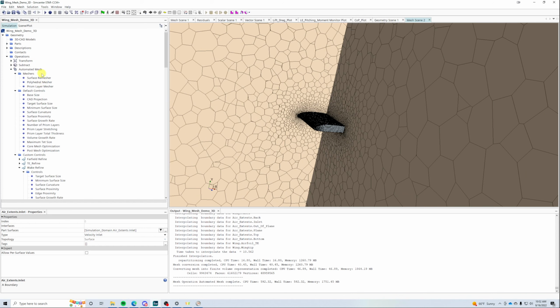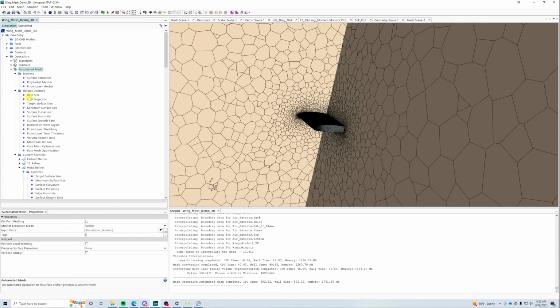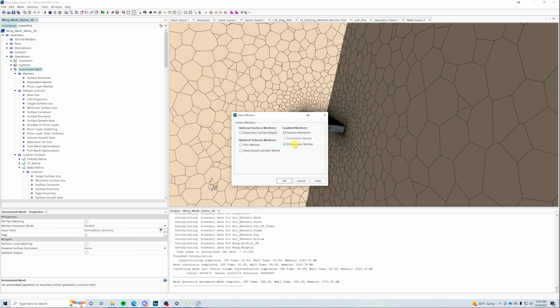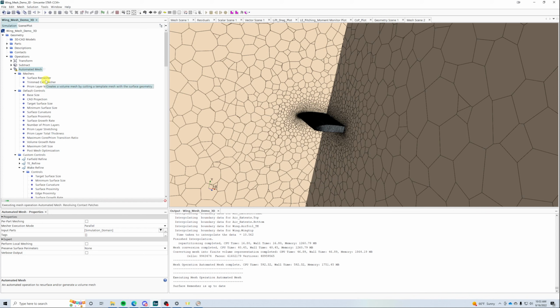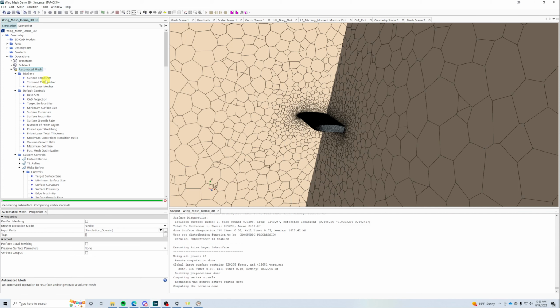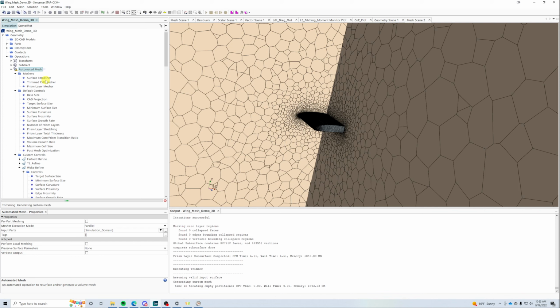Now, I wish I had an undo button. You'll notice the software doesn't have one. I'm going to switch this back to trimmer. The important thing about a trimmer mesh, which I'm not going to get the chance to show you here, we'll have to talk about it later, is that when it grows cells, it only does it in increments of 2. When it makes a cell bigger, it does it by a factor of 2. When it makes a cell smaller for the next layer, further away, it does it by merging cells or splitting cells, and it always does it by a factor of 2.